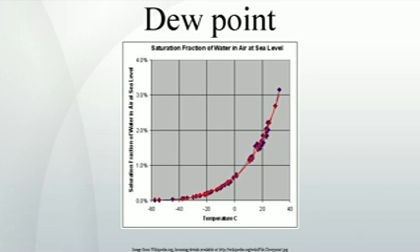General aviation pilots use dew point data to calculate the likelihood of carburetor icing and fog, and to estimate the height of the cloud base. At a given temperature but independent of barometric pressure, the dew point is a consequence of the absolute humidity, the mass of water per unit volume of air. If both the temperature and pressure rise, however, the dew point will increase and the relative humidity will decrease accordingly. Reducing the absolute humidity without changing other variables will bring the dew point back down to its initial value.